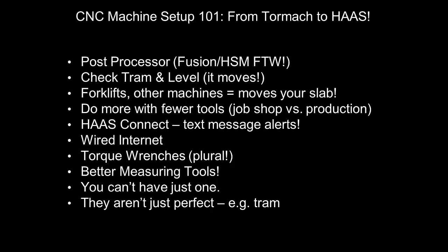Better measuring tools, we had to just pick up a taller linear gauge because we're making bigger parts. When we're trying to make better parts, you've got to figure out a way to measure those. Was not something that I had anticipated we would need so quickly, but there's no point in having a really expensive machine and doing higher-end work if you can't prove it or check it. You can't have just one.